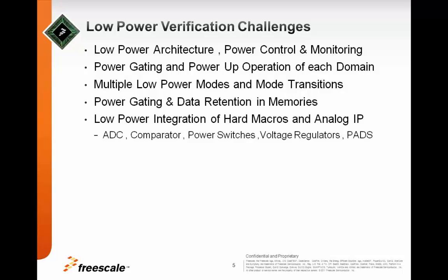Also, the seamless operation of low power peripherals across the mode transitions as well as various memory retention modes further adds to the verification effort. The low power design for test and testability, reset controllers, and logic-based controllers in each power domain further increases the scope and the debug challenges for functional verification at the RTL level.